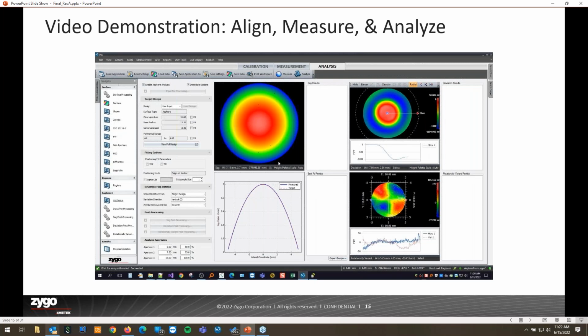Maybe it's a diamond turning optic that you're producing, and this will indicate that you may have something happening when the spindle is at a 9 o'clock position or a 2 o'clock position, so that you can identify that and make those adjustments that you need to make in your manufacturing process. The same could be true for, say, an aspheric polisher or even a mold plate.